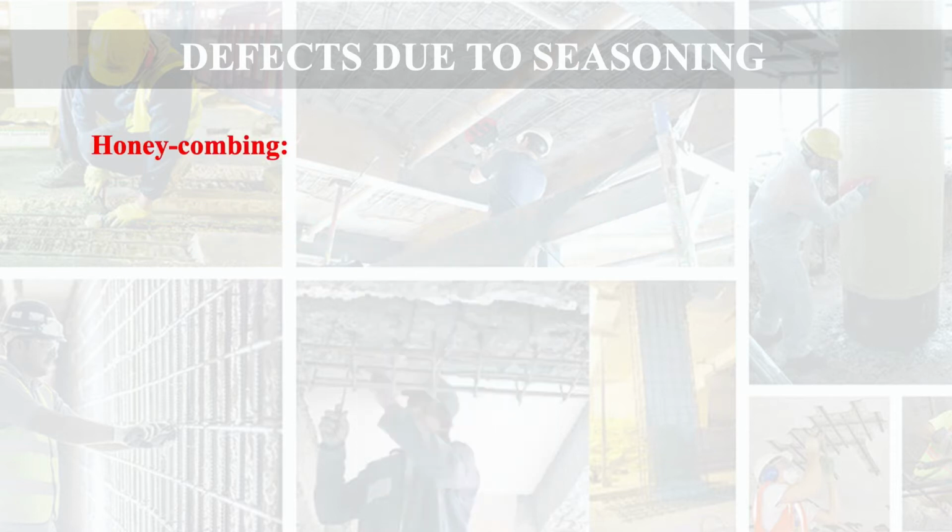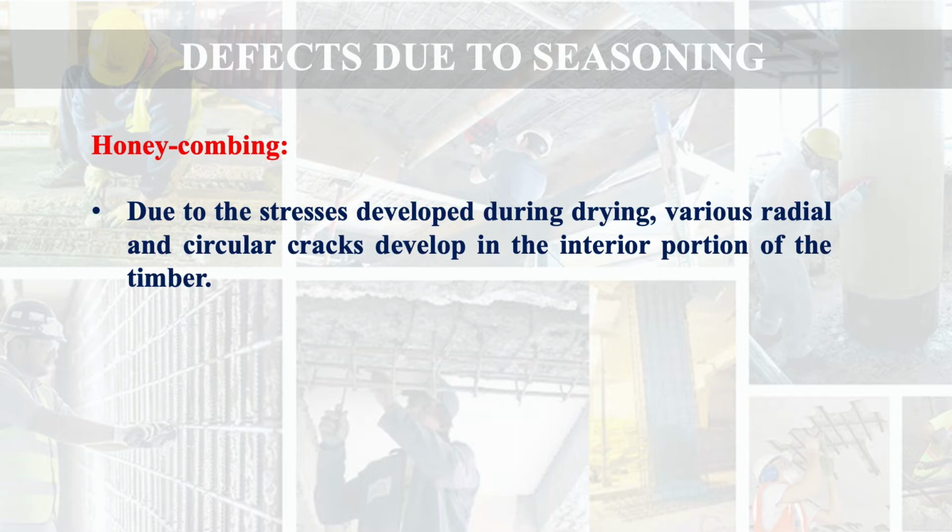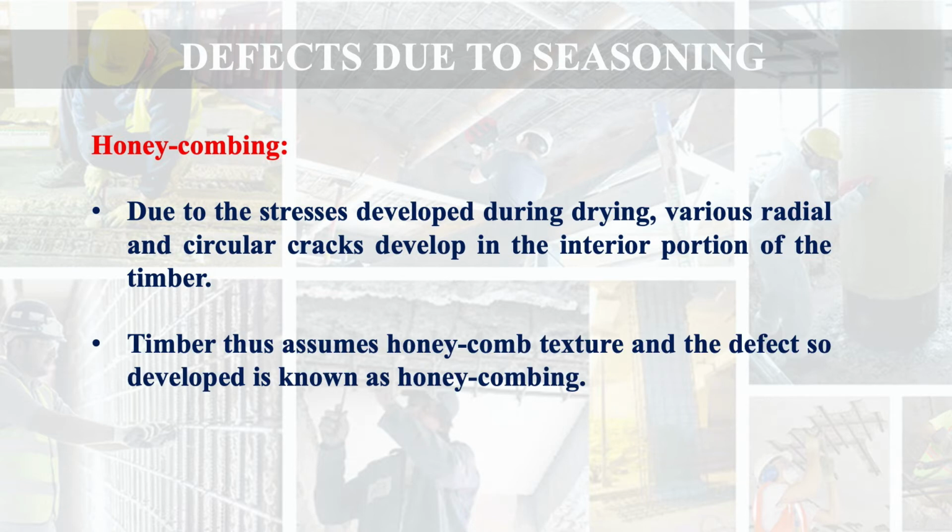Next defect is honeycombing. Honeycombing is due to the stresses developed during drying, and various radial and circular cracks develop in the interior portion of the timber. Timber thus assumes honeycomb texture, and the defect so developed is known as honeycombing, and the texture looks like a honeycomb.